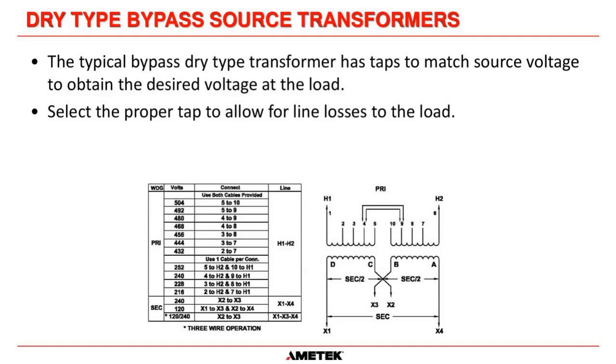Typically, when we set up our UPSs, and I'll refer to a single phase system here, we're going to set the output of the system up. If it's specified at 120 volts, we'll set it up so we run a little bit on the high side, somewhere around 121, 122, maybe 123. And the goal then is to take into consideration the line losses between the UPS and the actual load, so that at the panel board we're feeding, even if we've got some cable drops, we still have a good 120 volts there.